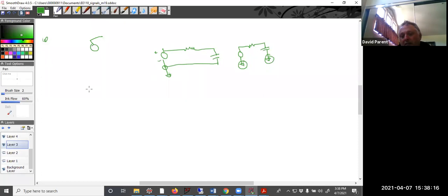If I had, and then over here I put node 1 in, LTspice would simulate this, and it just connects these two without putting a wire there. That way it can actually make things look simpler, right? Of course, you need a physical wire to truly connect it, but in LTspice or schematics, you can use node names to simplify things so you can see it better. And ground is just a special node name.